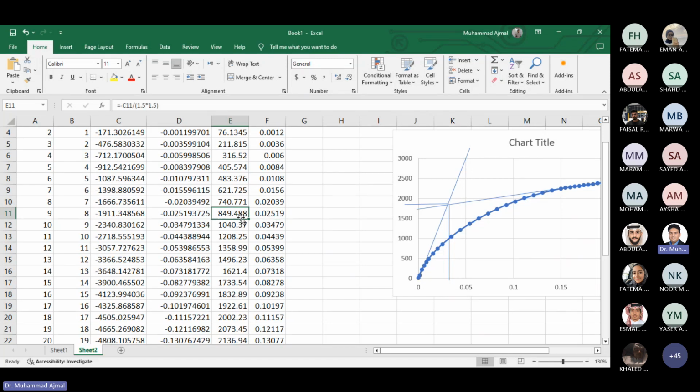So you can directly see the stress here against that settlement, which is around 849.48, which is the ultimate capacity corresponding to the 25 millimeter settlement. And you can divide this by 3, and you can reduce your allowable capacity to 283. So you can see how you can figure out the bearing capacity directly from the usage of the Plaxis 3D software. So this is the simplest example.